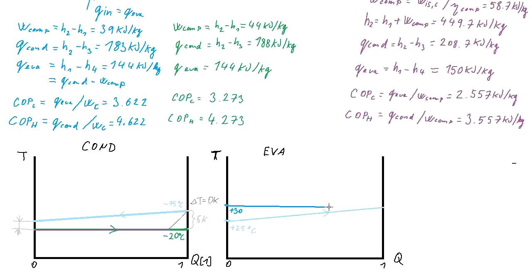So the temperature profile would look like this up to a certain point, from which there was some desuperheating, where the desuperheating took place from the temperature of 38 degrees C. So again, you can see that we might come into trouble because the minimum temperature difference that we wanted over here would result in a much smaller temperature difference at the point over here.